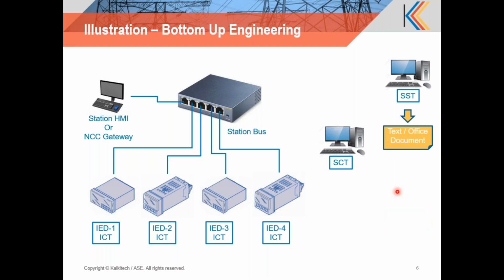The bottom-up approach also starts with a specification, except that typically it is the traditional specification that is used now in the form of office documents. It's got tables and figures and clauses and information. So it is still used by the SI role, the system integrator role, but it's not really used by the SCT. Please note the direction of the arrow that I'm showing here. It is information for the system configurator user, but it's not information that can be processed by the SCT, because the SCT only understands files written in the substation configuration language.